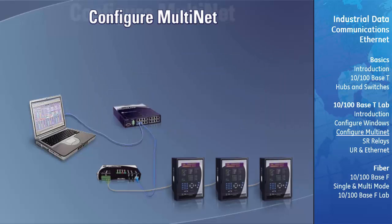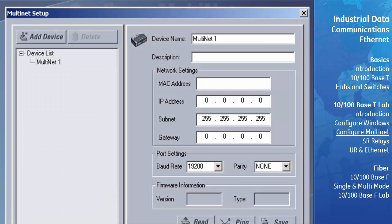To configure the MultiNet, launch its setup software, which can be found on the GE Multilin product CD or website. Enter the MAC address found on the MultiNet label, in addition to a unique IP address. We will enter an IP within the range of our test network addresses. Next, enter the subnet mask. Here we will enter our test network address. The gateway address would only be added if one existed.